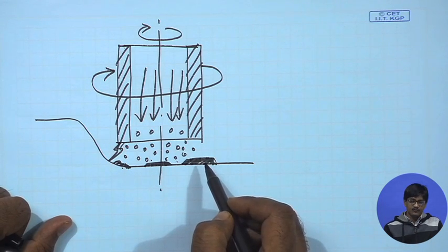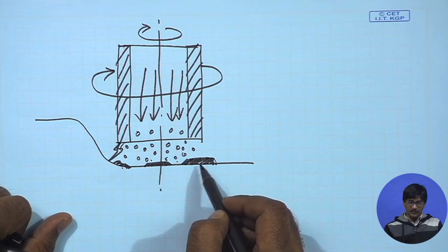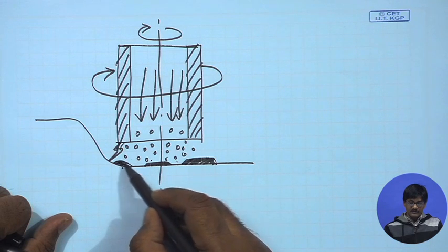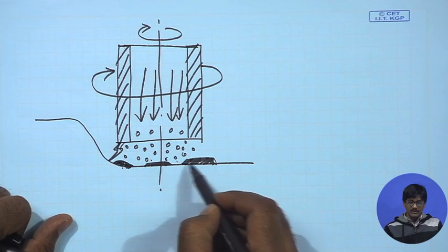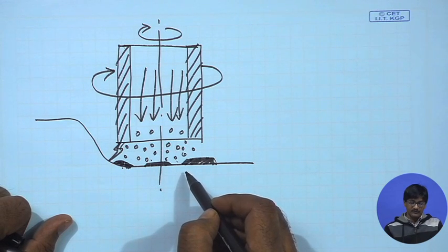This has a twofold advantage. First of all, the abrasives will be removing the recast layer, which is detrimental for surface quality, and secondly, material removal rate will rise. And it has a threefold advantage.